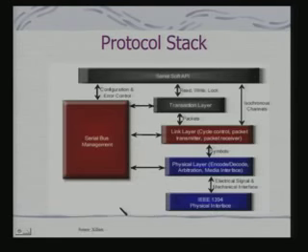So what is a protocol stack? It is a pretty sophisticated protocol stack, not as complex as that of any networking layers, but still sophisticated. At the lowest level you have the physical interface, which provides the electrical, signal and mechanical interface, just like any bus structure we had discussed earlier. Then you have the physical layer, which provides the encoding, decoding, arbitration and media interface, because the data, when it has to flow in and out, has to be encoded and decoded appropriately.